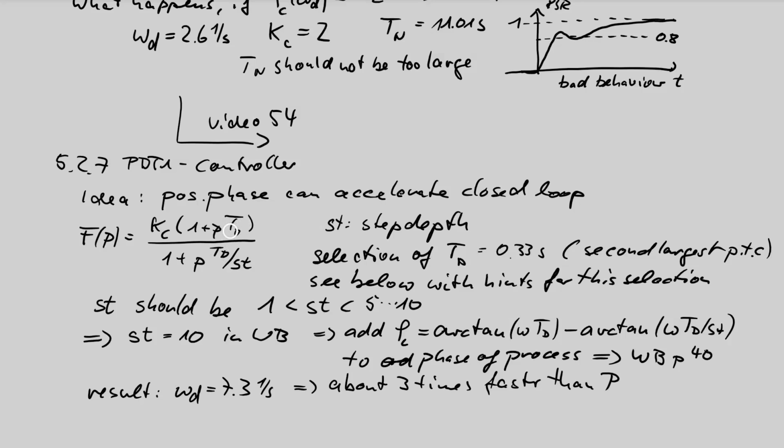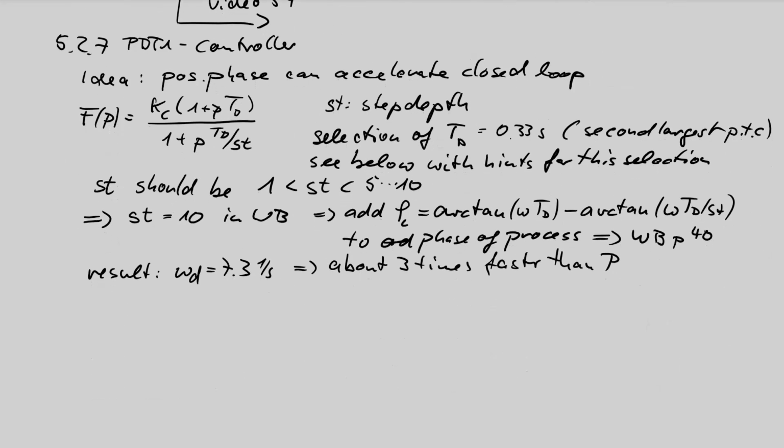So with omega D, the only thing missing is Kc. Again, Kc with the magnitude equation of Nyquist, that the total open loop gain at our now calculated omega D crossover frequency is 1.